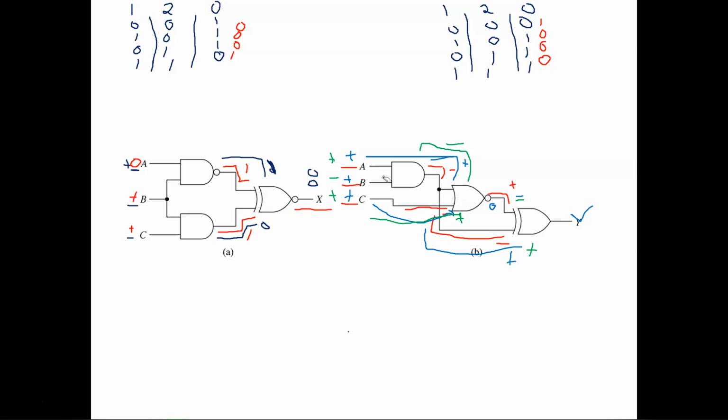So whenever you're dealing with these, it does really pay to know which one of these gates does what. So with an AND gate, you have to have the idea of what you're tied into after it. So in this case, we have a NOR gate that's tied to an exclusive OR gate. So knowing your truth table for an exclusive OR gate, which again is what? He wants both his signals to be opposite, right?